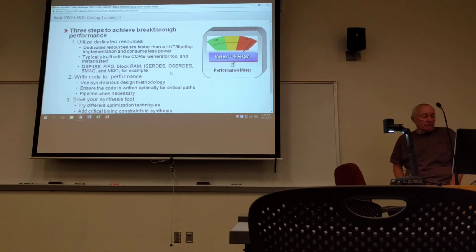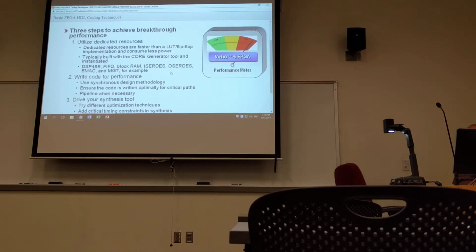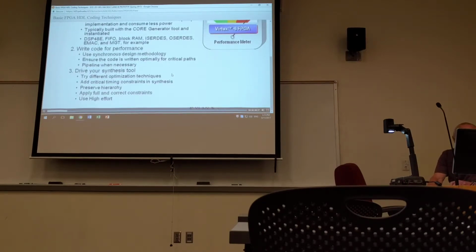Writing good HDL is of course important because it is used by synthesis tools to infer the most popular FPGA resources, that is, LUTs and registers. Since there's very often more than one way to code for effectively the same functionality, it is important to understand the differences between two or more ways to code a function. This is compounded by the fact that often a poorly coded piece of logic creates a timing critical path for a designer to resolve later on, and often designers waste a great deal of time resynthesizing and repeating a place and route solution, hoping to meet a timing objective.